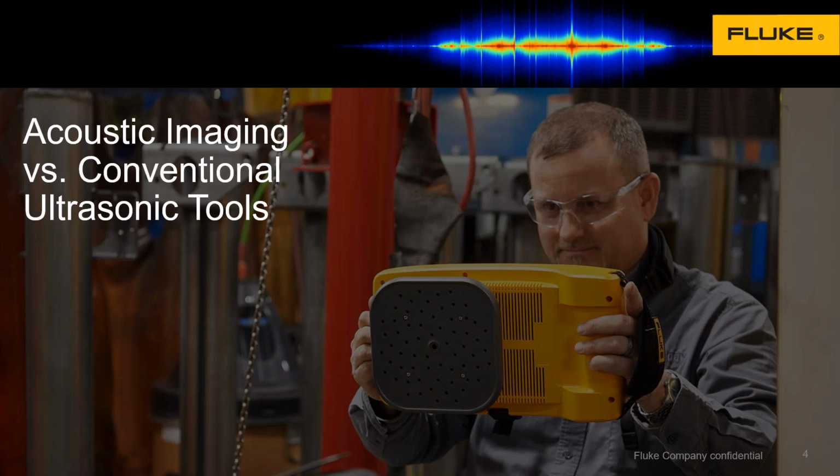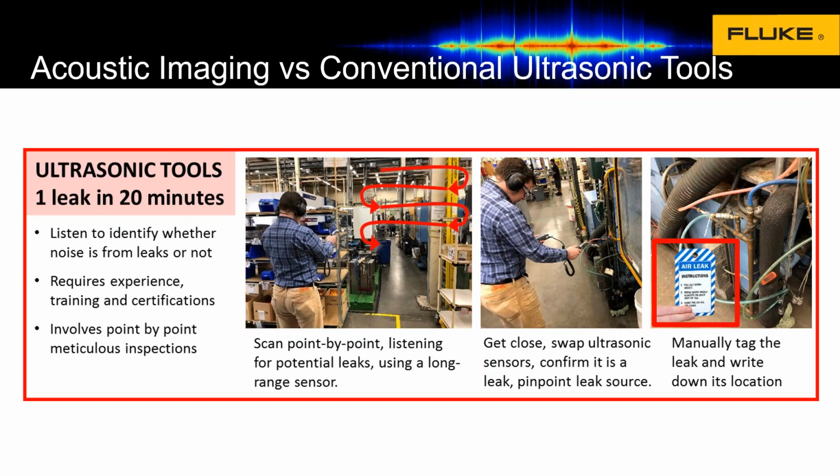Okay, so some of you are saying, oh yeah, I know about acoustics because I've been an ultrasonic specialist for years, and we've used ultrasonics to find leaks for many years. This is not new technology. Well, it's a little different. As I said, we're dealing with sonic and ultrasonic, and we're dealing with a broad spectrum. We're not just dealing with 48 kilohertz or 43 kilohertz or 34 kilohertz, which a lot of the ultrasonic tools do.